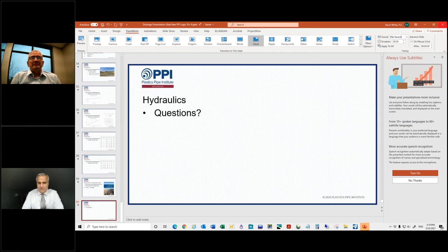Okay. I had a question about my statement of 28% void capacity in the backfill material and what that backfill material was. Typically, AASHTO 57 stone is a clean 3/4 material. It has a void ratio of approximately 40%, and I think that's maybe the number that a lot of people are more familiar with. But the resulting porosity of it is 28%, and that means that 28% of the total backfill volume can be utilized for storage. And so that's what we're using.